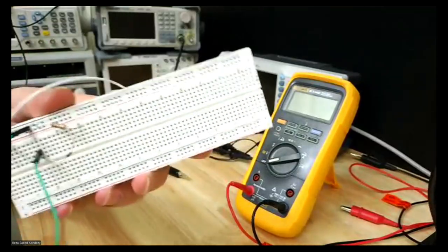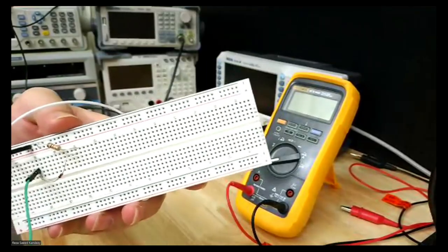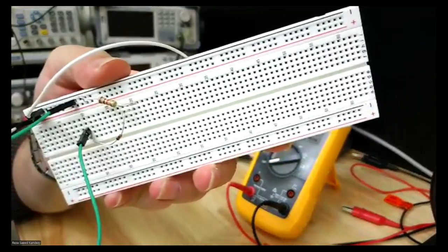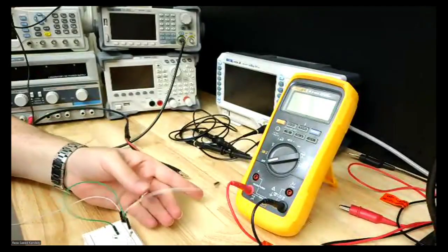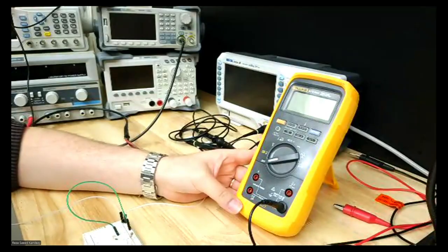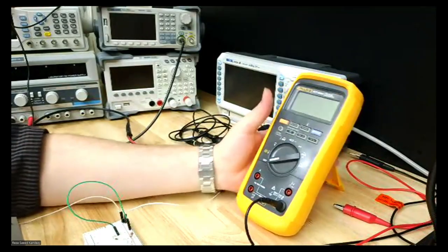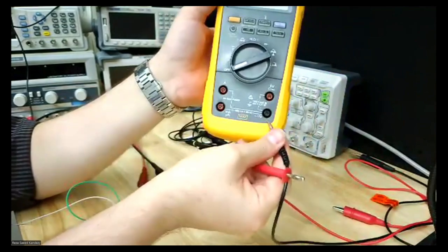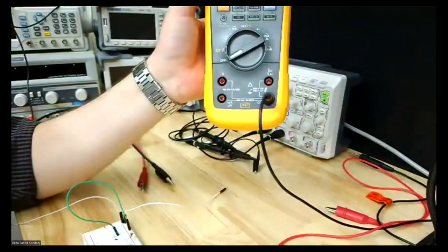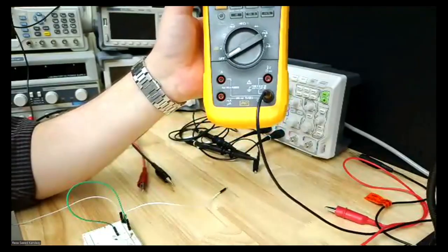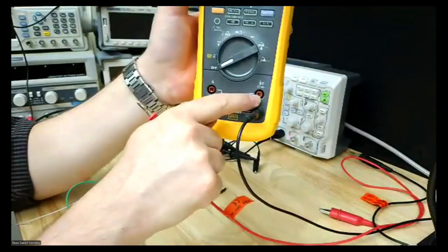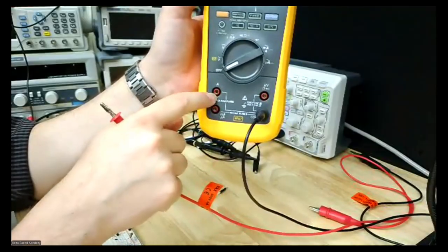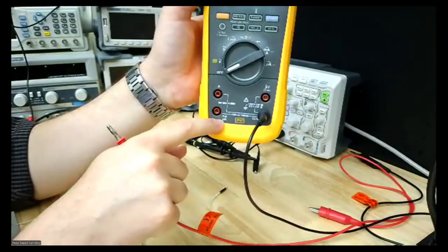Okay, now before I start the circuit, I wanted to make sure I chose the 1 kilo ohm resistance based on the color codes on the resistance. Okay, but I want to make sure that it is actually 1 kilo. So I'm going to use the multimeter. You can see the probe here. We have the common probe, which is the black coded. We connect the common probe. We have three measurement probes. One is used for volt and ohm. The other two are for amp, but different ranges. One is the amp range, another one is milliamp and microamp range.